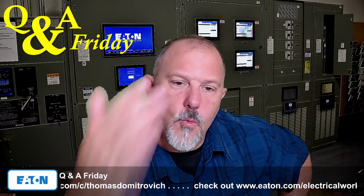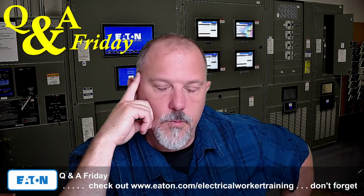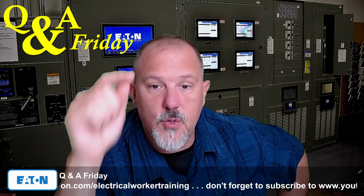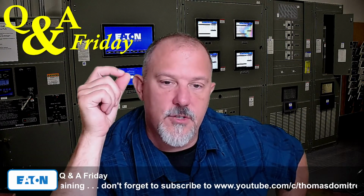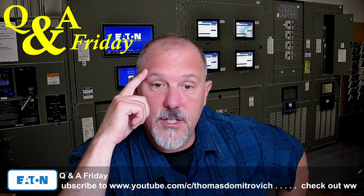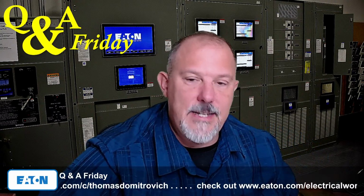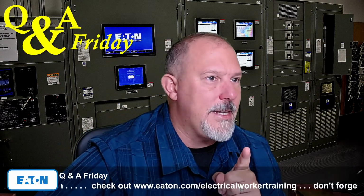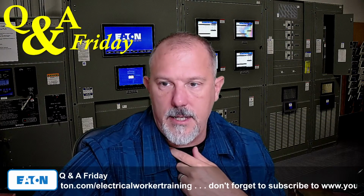A citizen of our world says, 10 hours ago, the way I learned it, I would have interpreted 1 minute and 27 seconds, this is in the circuit breaker selective coordination tables, to mean the 20 amp breaker will trip first as it is farther to the left on the timeline, and the instantaneous regions of these breakers don't overlap. So as the short circuit current quickly rises towards 1,000 amps, would it not be interrupted before it exceeds 300 amps? Great question.